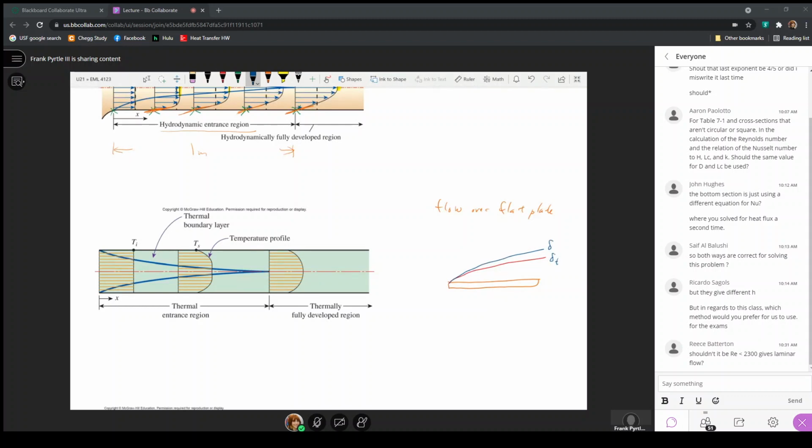They don't grow at exactly the same rates, but they do grow from the velocity boundary layer due to that no slip condition, in that the molecules right next to the surface have a zero velocity, and it's a fluid that is moving outside the boundary layer, so that for the velocity boundary layer delta, inside of that layer is where all of the velocities change and all of the velocity gradients exist inside that boundary layer.